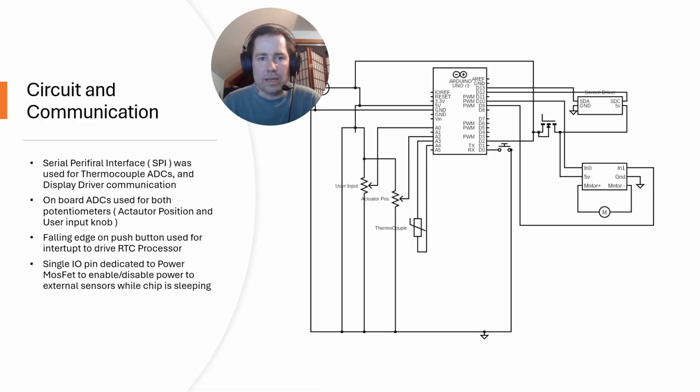The digital circuit layout was very simple. All chip communication was implemented via the serial peripheral interface. This greatly simplified the coding as well. Requiring only 2 I/O lines per chip meant that the circuit was very easy to wire, but limited the amount of data I could display on the screen. As I only planned to update the screen once per time step, this really wasn't an issue.